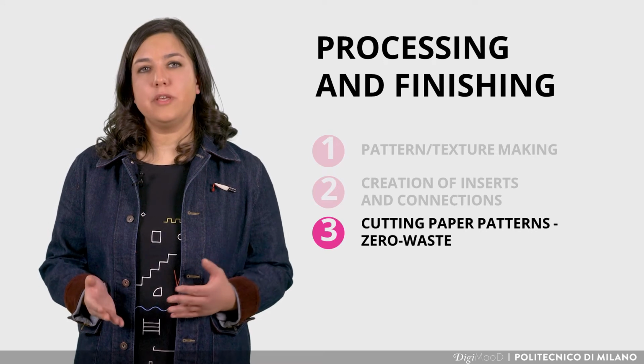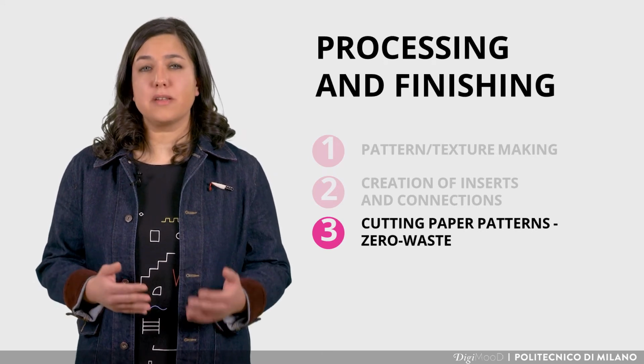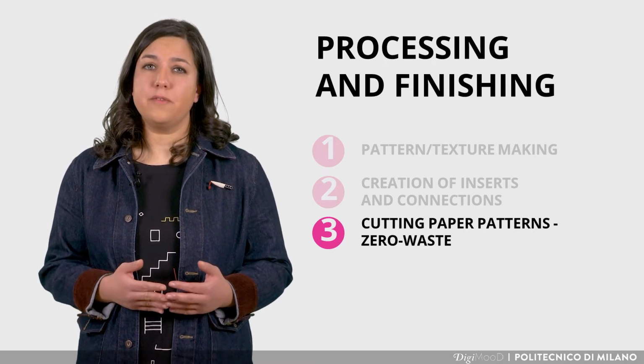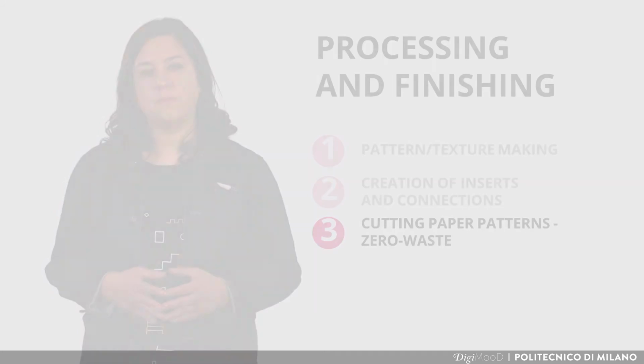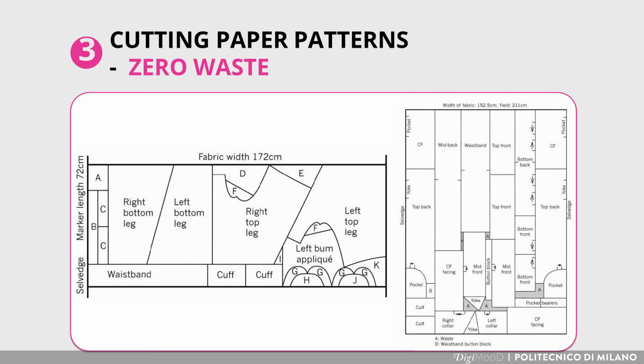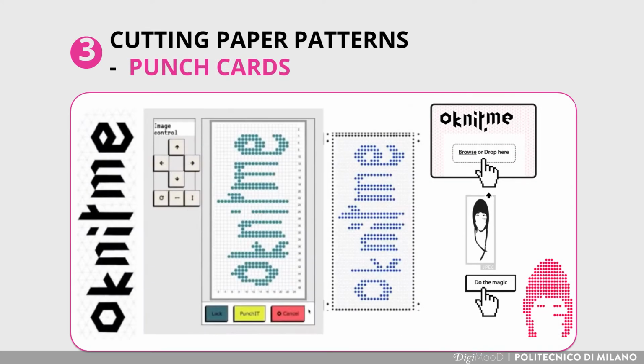Laser cutting can be used to cut the paper pattern directly onto fabric, paving the way for a zero-waste design approach. With the heat of the laser, in fact, the edges of fabrics based on synthetic fibers will be automatically welded, and the pieces will be usable without creating hems. In addition, with this machine you can also create customized punch cards to be used to make custom nightwear.